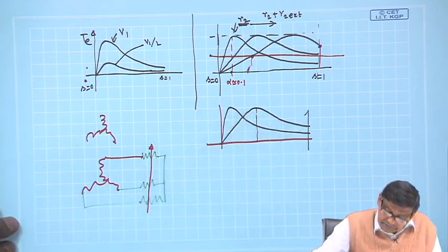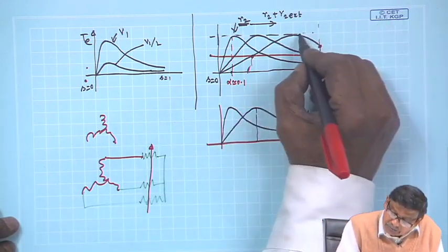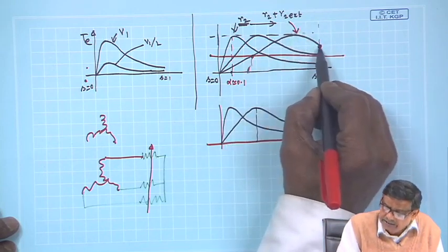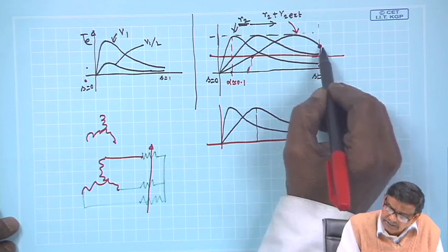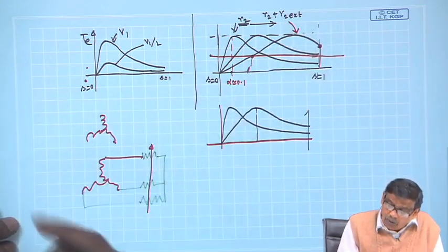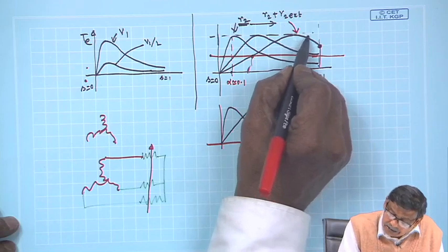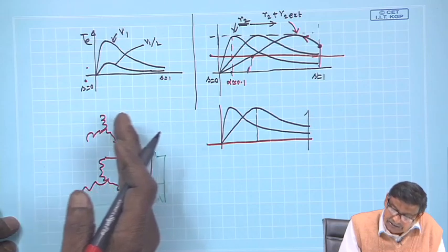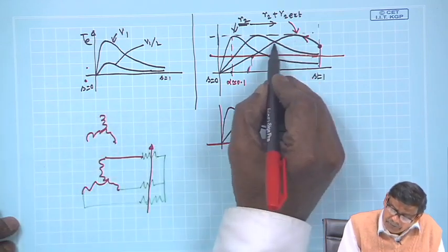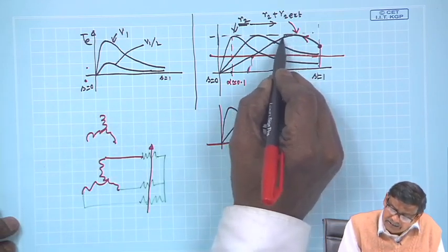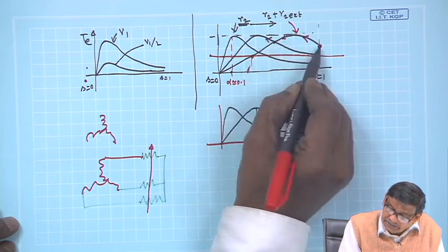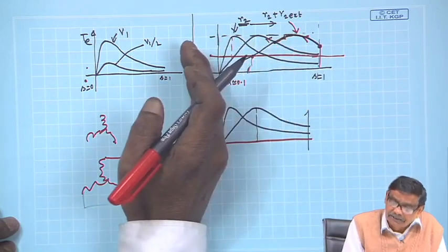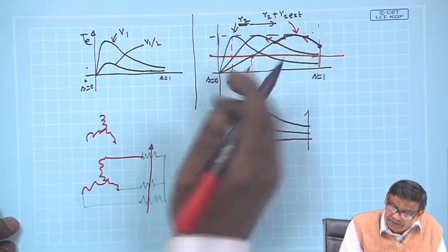Now, in this case, suppose this is R2, and R external you have connected, and you wanted this much starting torque, which is greater than this, so the machine will accelerate. How will the operating point shift? It will shift like this, but as it shifts, what do you do? You cut out this resistance. If you have cut out this resistance here, then it will travel to this, it will go like this. Suppose I reduce the resistance a bit, that R2 external, which is variable,